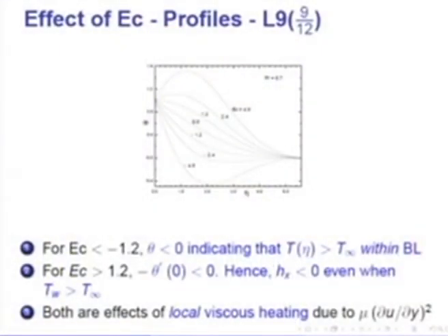That is why the re-entry vehicles are coated with ablating materials, so that when the heat transfer takes place inside and the surface temperature goes up, the material evaporates and carries away the heat which has been ingressed from the outside into the wall of the re-entry vehicle. So, study of such effects is of great consequence in practice.